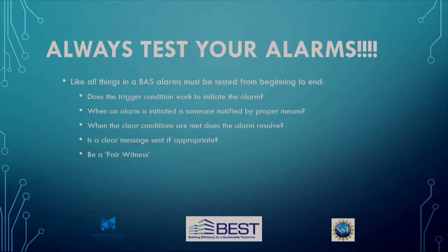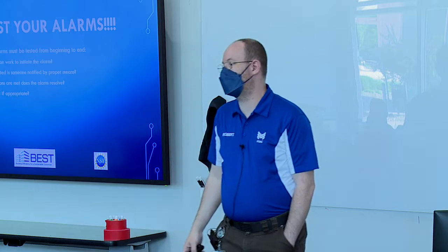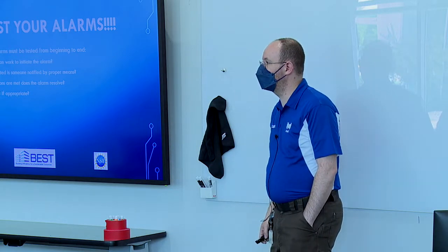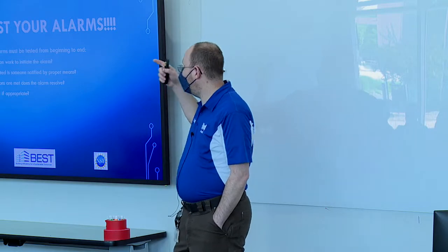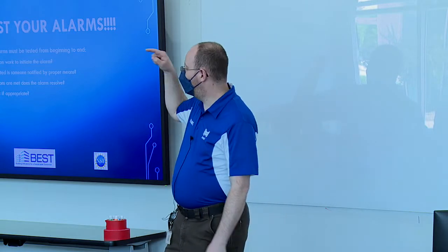Always test your alarms. Drive this into the students' heads. Stomp it into them. Always test your alarms. As far as I'm concerned, a building tech or automation system technician, part of their responsibility is to test everything in their system. If I'm telling a fan to turn on, it better turn on. If I'm telling it to turn off, it better turn off.